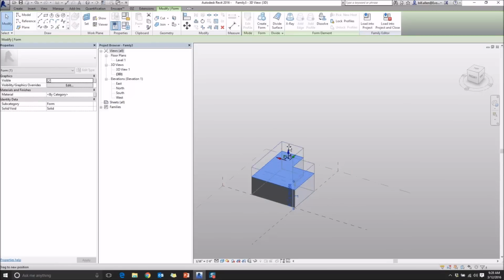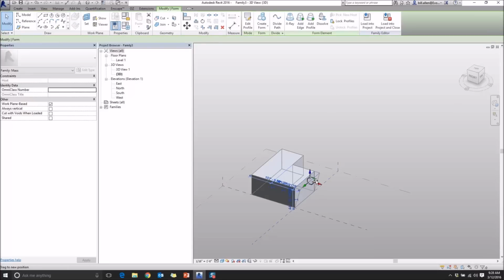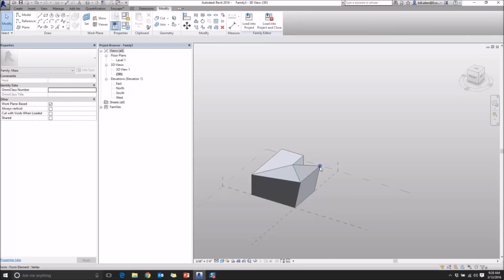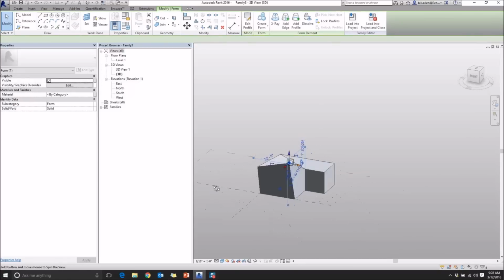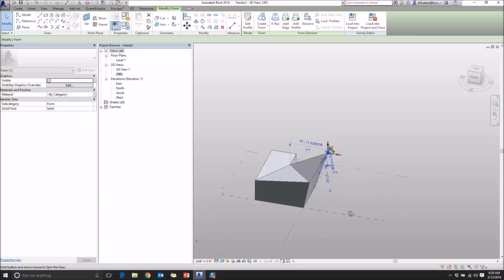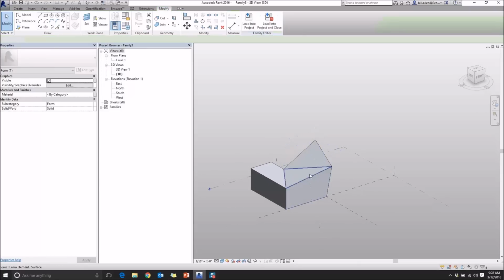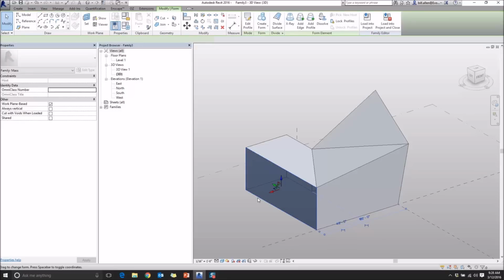And it's going to basically extrude that form up. And so what we can do is we can start pushing and pulling the faces, not only the faces, but you can also push and pull the vertices on here. And then you can also grab the individual points and push and pull those as well. Just like that. Okay? So this is how you can start interacting with some of this conceptual geometry, just with pushing and pulling, very similar to, say, SketchUp or other massing programs.